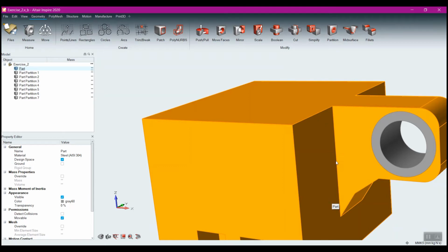There's a possibility we can have some higher stress in these corners here because we don't like sharp corners, but we're not worried about that right now. What we're worried about right now is getting that design space defined. And we want it to be as nice and big and blocky. And if you want to know the details behind that, the smaller the features you have on your model, the smaller the mesh has to be, and the longer the analysis of the optimization is going to run. So we don't want to mess with small features right now. We just want large, big blocks of material. And from that, the optimization code is going to determine what is necessary.